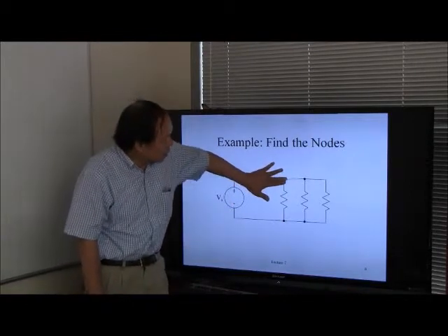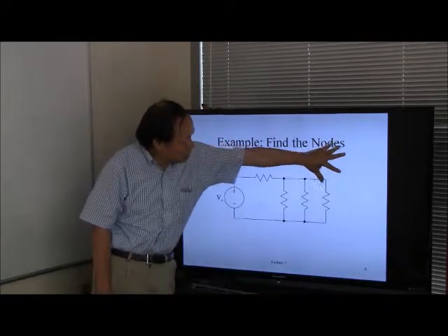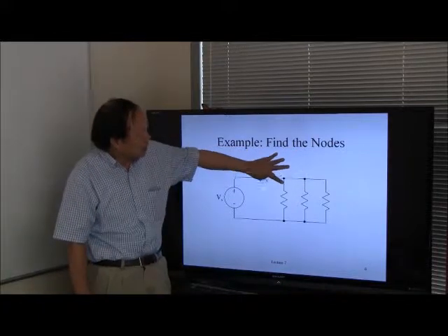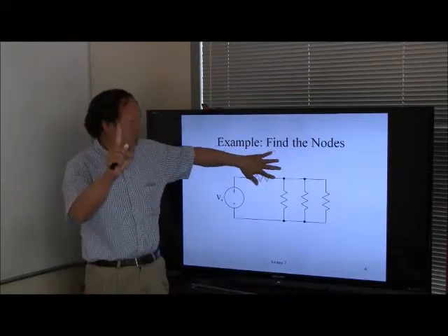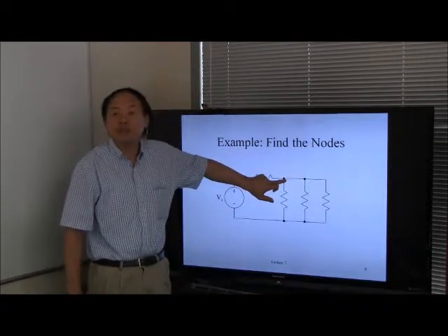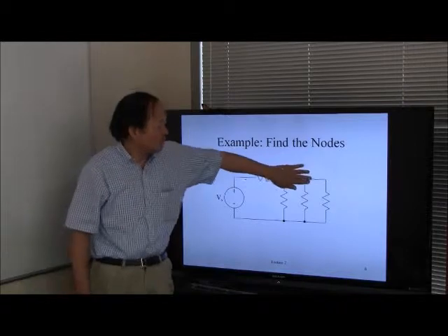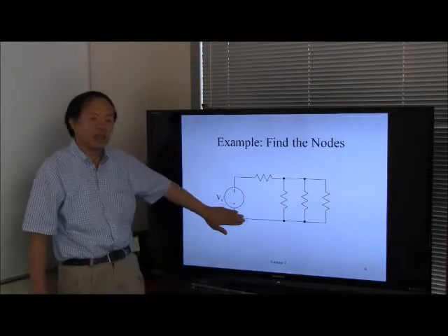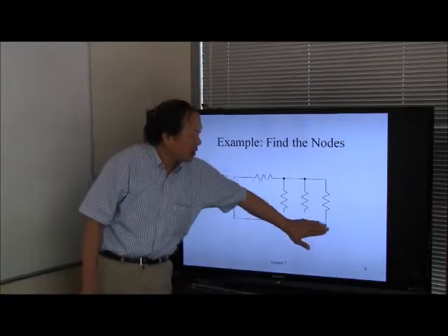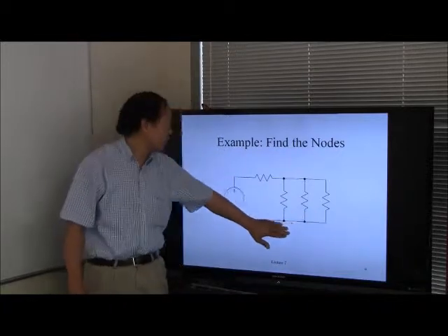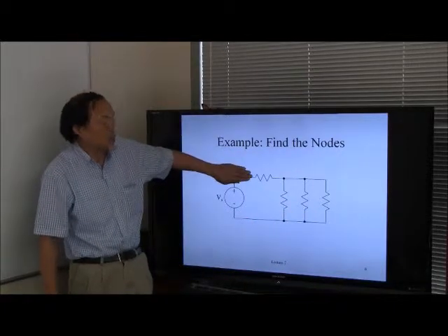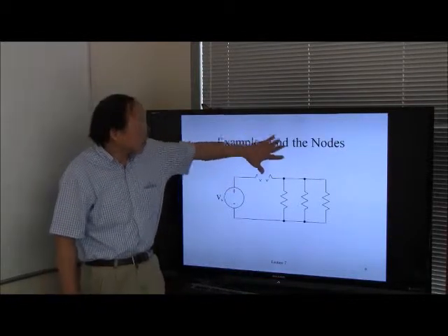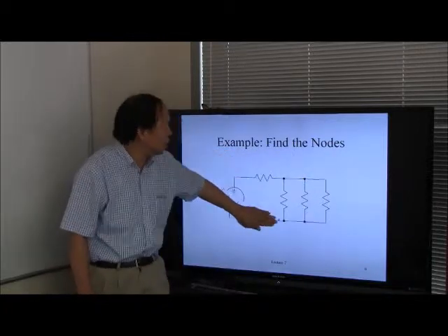1 node which is effectively, if you move along these wires not entering into elements. So all these wires comprise one single node. You shouldn't look at intersection points of the wire to say they are two nodes, but this whole thing is one single node. Whereas this bottom part of the circuit is another node, because you can move along the wires before you encounter an element. There's a second node, and the third node really doesn't look like a node, it's really this node here, because it's part of the wire between the voltage source and this resistor. So the nodes in this case are one node, two node, and three node.